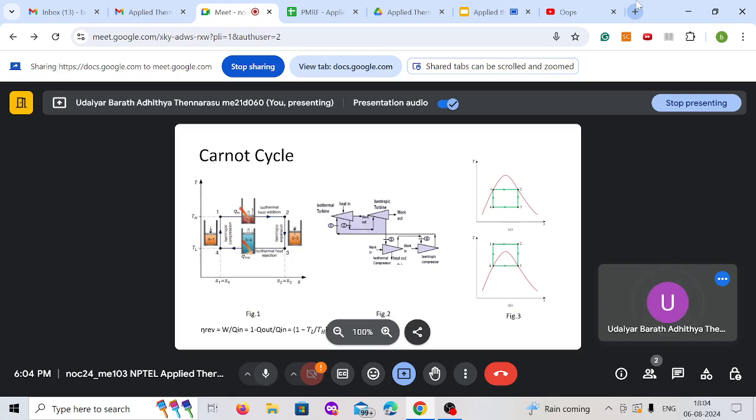Again, I said an adiabatic process has to be very fast. An isothermal process has to be very slow, happening slowly enough that it rejects heat and comes to equilibrium at a constant temperature. So seeing the cycle, it has 2 processes which are very fast and 2 processes which are very slow. Having this is one of the problems in a Carnot cycle, physically speaking.